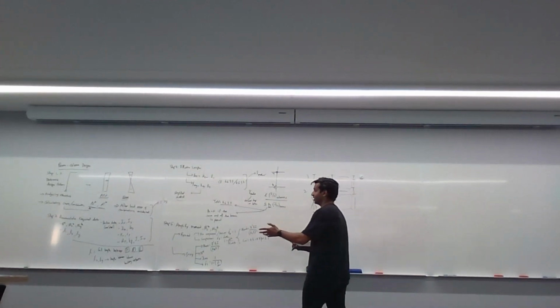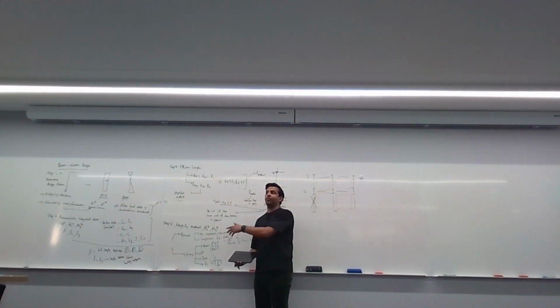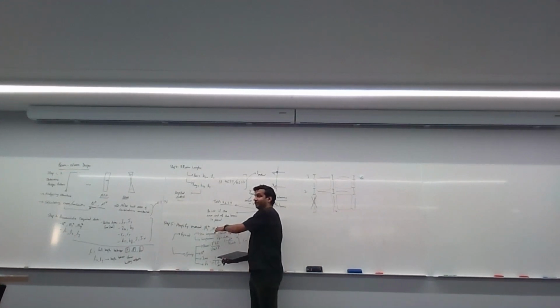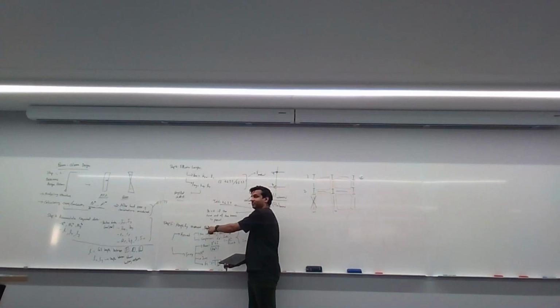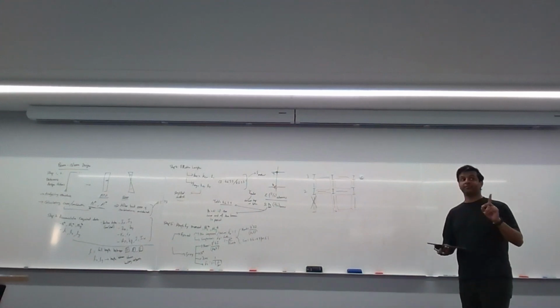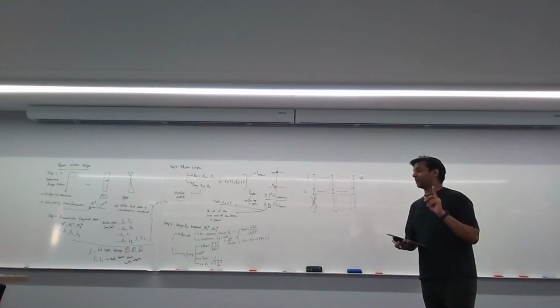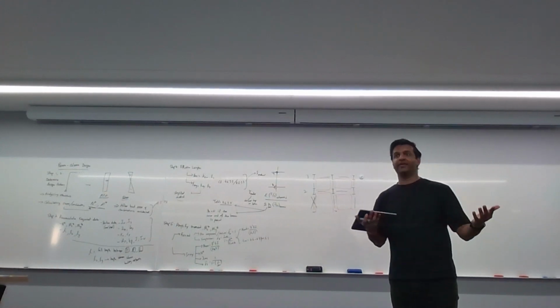So if in one direction it's braced and in the other direction it's swayed, what do you have to do? Let's say Mx is braced and My is swayed. Then for My, because it's swayed, you use the sway part, and for Mx, because that direction is braced, you use the braced one. You just use the appropriate one. Although generally speaking, the direction that's braced is always the weaker direction, which is the Y direction.